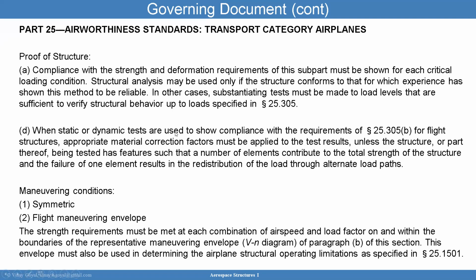When static or dynamic tests are used to show compliance with these requirements for flight structure, you have to appropriately correct the loads with the correction factors. And that means the test-like flight differences that we talked about. Maneuvering conditions like symmetric and flight maneuvering envelopes need to be considered.